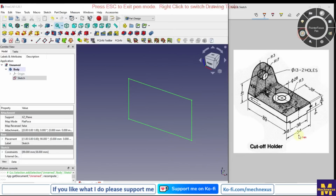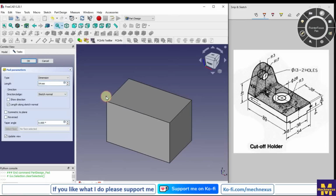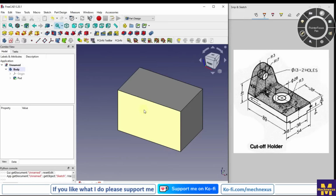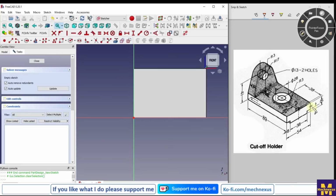Now the total width here is 54, so I will go for the pad and give 54, and make it symmetric to the plane, and say OK. And now I will select this face and say sketch. We can see here the thickness is 13 mm.